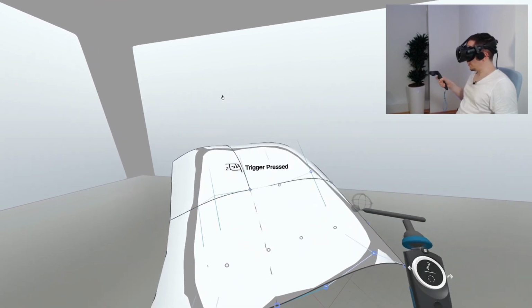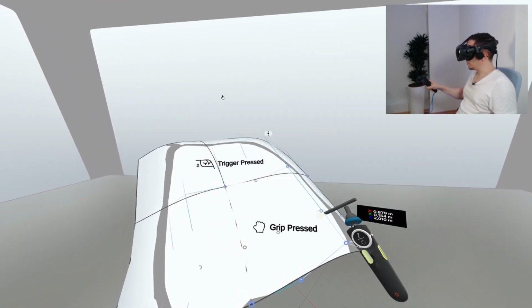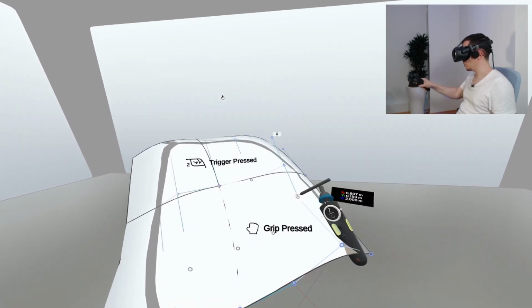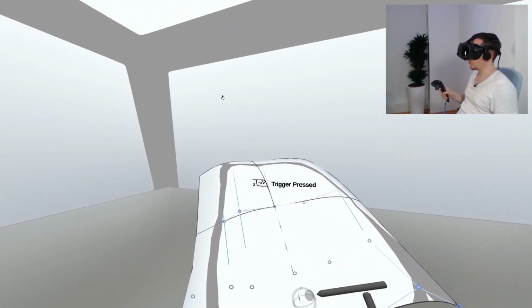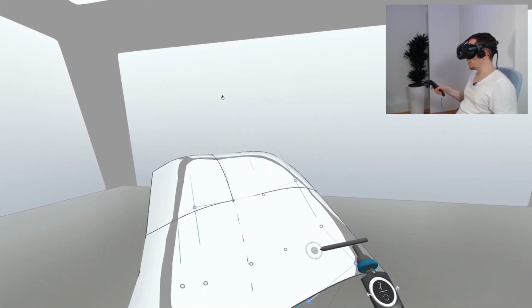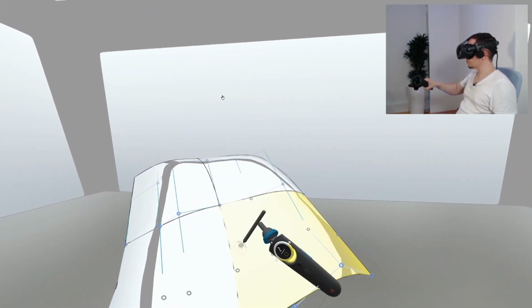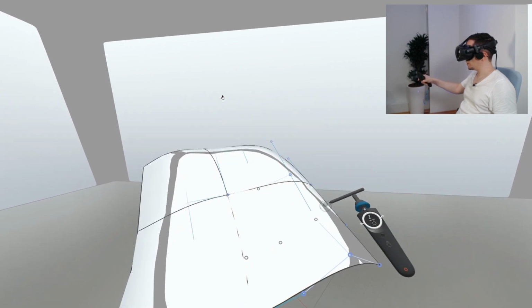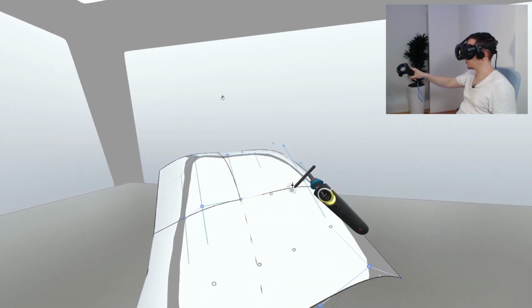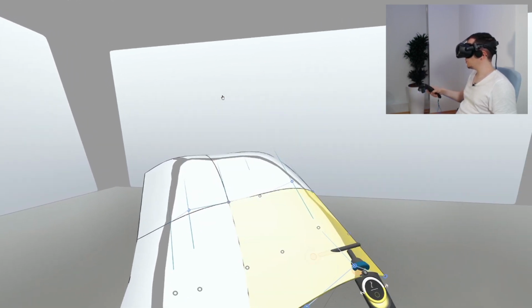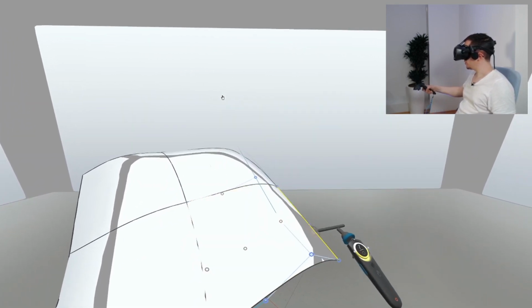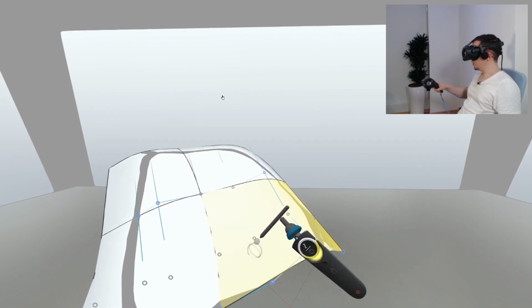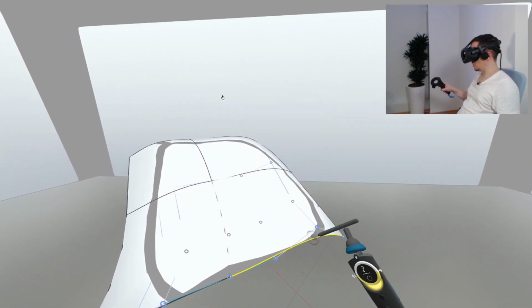Now one of the effects is of course when I change something, my adjacent patches change as well, because otherwise the continuity would not be the case anymore. So you need to be aware of this. And if you want to have more freedom in the design of one patch or one surface that has this continuity link, you may need to add more CVs in the respective direction. So if I added another CV here, I'd have more freedom at least on this side of the patch.